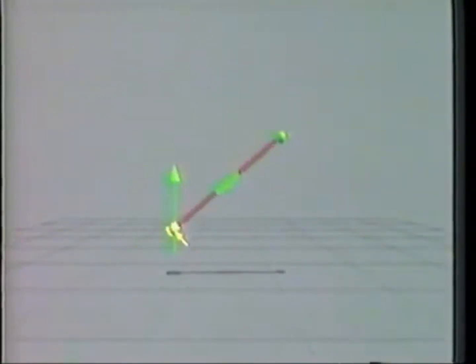Now the endpoint is linked to the ray, and it turns yellow to indicate that it has been partially constrained. We use colors to indicate the degree to which objects are constrained. The point is now constrained to lie on the ray. This process of establishing relationships is called linking. We similarly link the other endpoint of the length widget to the same ray.